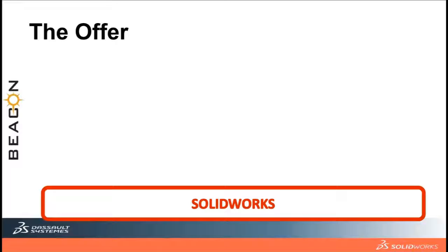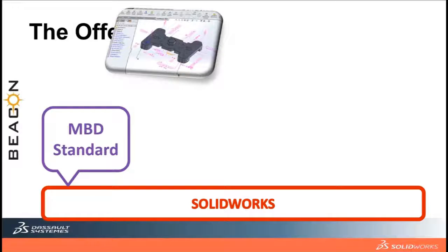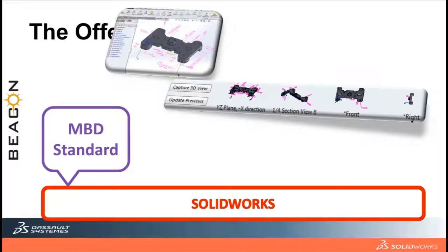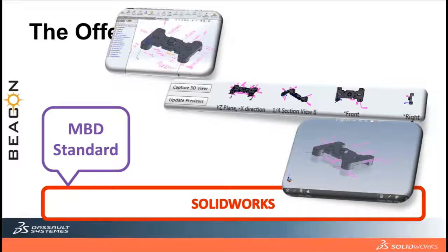So what we offer in terms of SolidWorks MBD is we can directly add the information, the PMI, onto the model, and we can organize them. We can have all the views similar to the 2D drawings with greater clarity in terms of your section views, detail views, or even the views that are required for manufacturing. And finally we can publish it in n number of ways, as you saw: we can do it for a PDF, we can do it for eDrawings or STEP 242 as well. This will also give more clarity for the person who is reading the drawing.